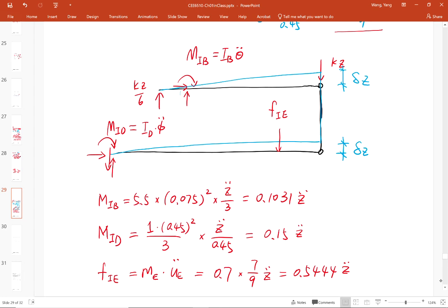So this should be the complete free body diagram. We have all those forces and moments. We can also give a name. This is the spring force, FSA. I can call this FS at C, if you like. The spring forces.